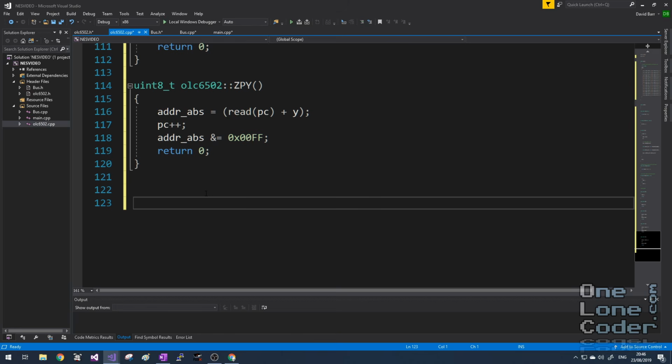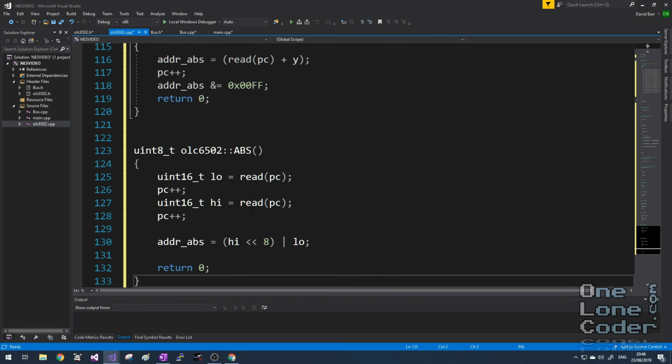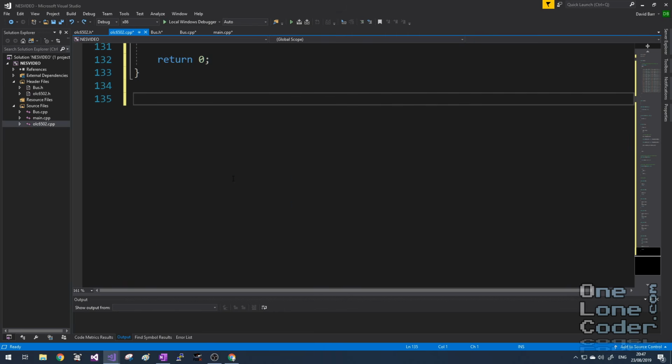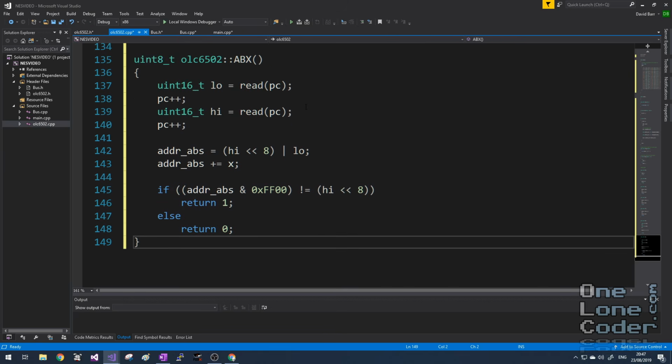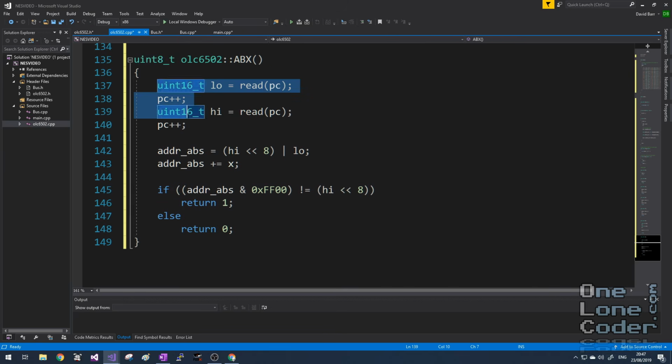Sometimes you just need to specify the full address in its natural form. So the address supplied with the instruction, and it'll have to be a 3-byte instruction for this, consists of the low byte and the high byte of the address. I OR these together to form a 16-bit address word. In a similar way to the zero page with offsets, we have an absolute address with X register offset. We read in the base address and we offset it by the contents of the X register.